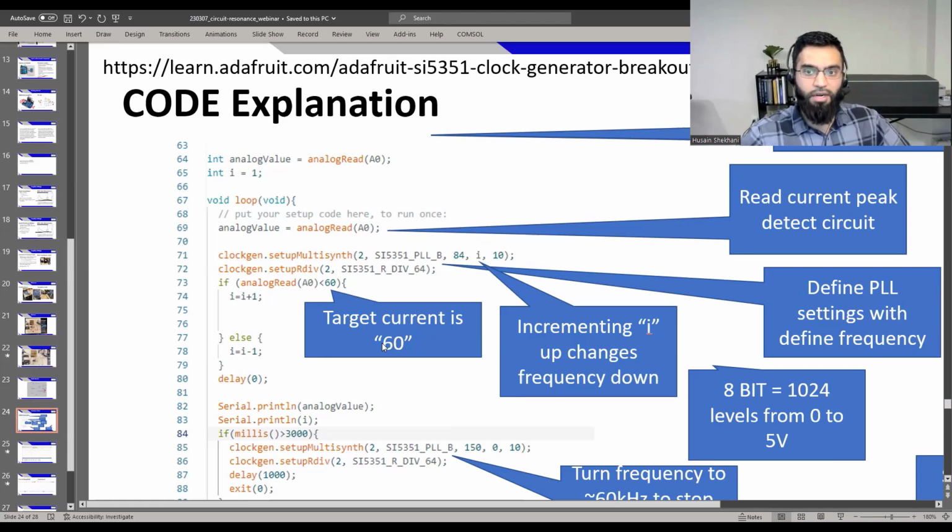Dropped over the diode. That's another reason I used the output side for the current measurement, because a diode on the primary side would really drop a lot of voltage, like 0.7 volts. That might be the whole voltage you're trying to measure. And also, if I put a resistor there, that resistor would dissipate power, and that's not good. It's better to do this on the high impedance side, the secondary side.